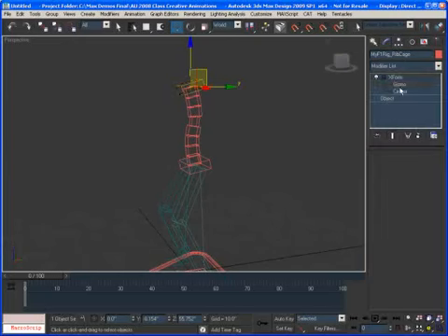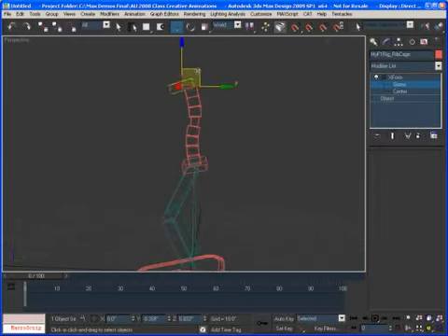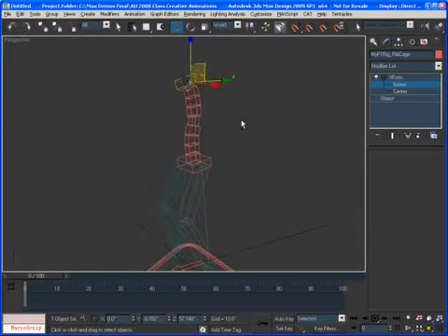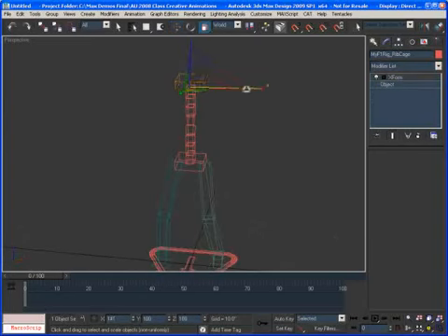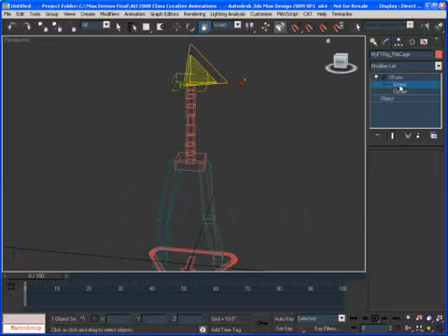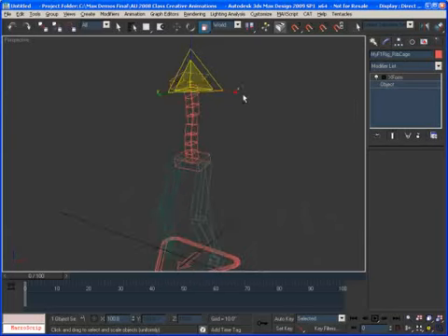And you grab the gizmo and then you can place it where you want it to be. This will not affect the pivot point of the rib cage. It's going to still behave correctly, but you can at least visually place it wherever you want it to be. So what's important to know is that if I grab the object itself and I scale it, it's going to affect the position of the clavicle when it's going to attach to it. But if I go in and I use the gizmo, it's not going to affect the position of the clavicle. So that's a difference between the two setups.